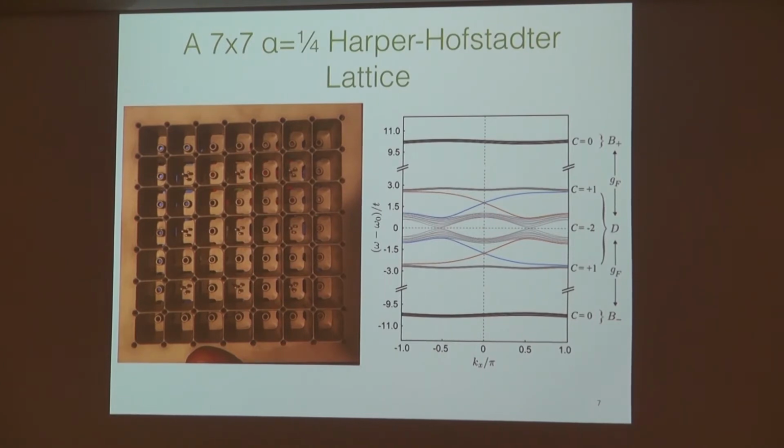Do you ever reverse the magnetic field and do it backwards? Or is it designed to go one way? So here's what I can say. If you excite in the lower gap, it goes one way. If you excite in the upper gap, it will go the other way. Now, you're saying, why don't we excite in the lower gap and then flip the magnetic field? Well, the way this thing is actually implemented is we have a rare earth magnet placed beneath each one of these chiral sites. So flipping the magnetic field is kind of a pain.